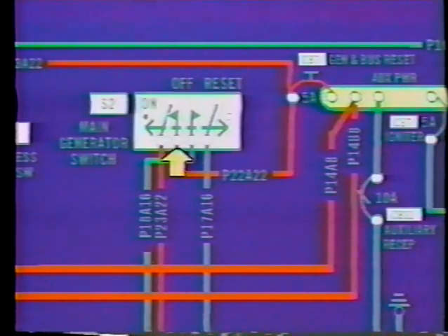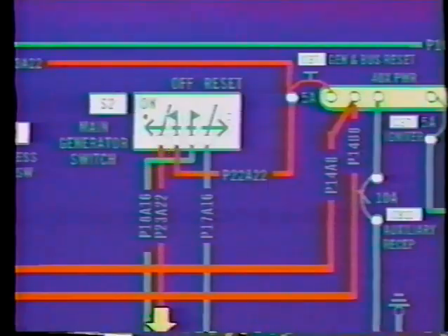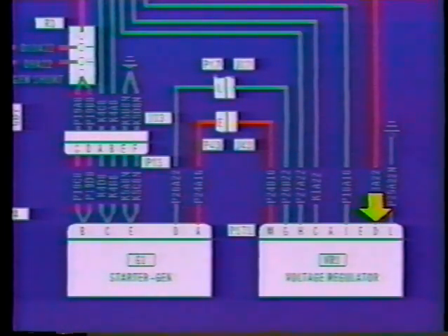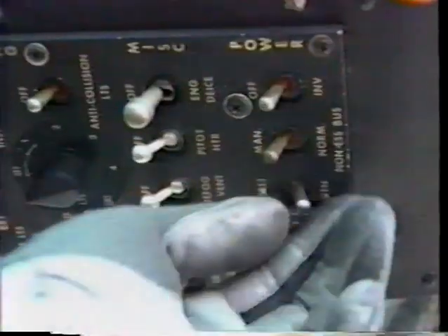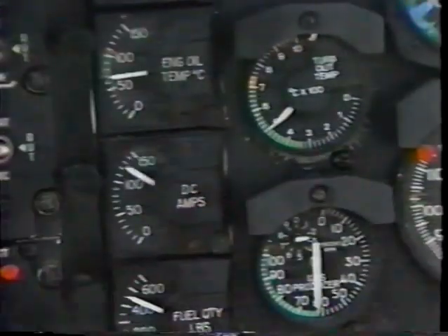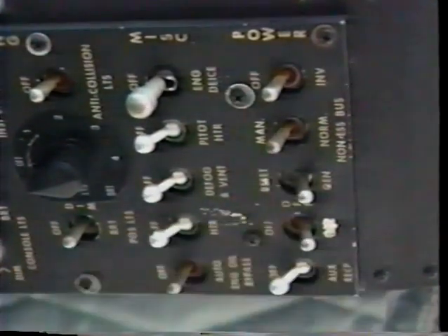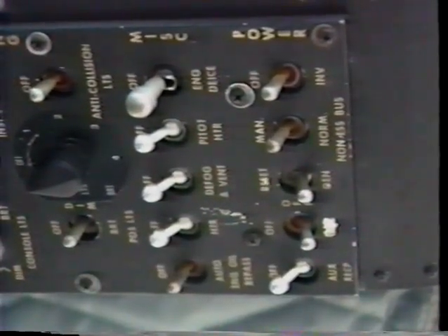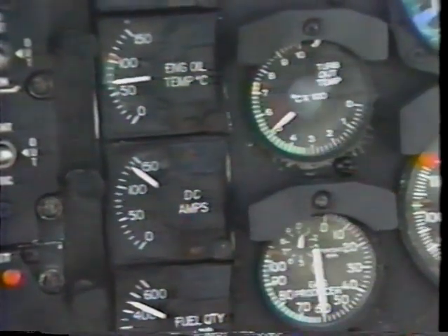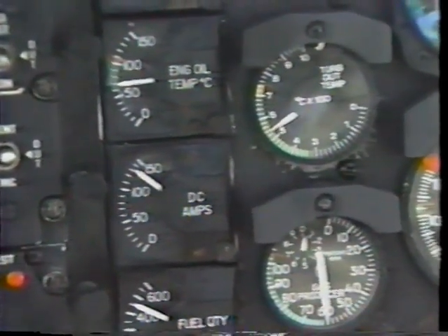This action will allow the waiting battery power at the generator switch to travel through the generator switch to the voltage regulator's pin D. At this time, that same power is sent through the voltage regulator, leaving the voltage regulator at pin M, and arriving at the generator via pin A. It only takes a moment to flash the field. At the completion of this procedure, return the generator switch to the on position. This will allow the generating cycle to be repeated again as previously explained.